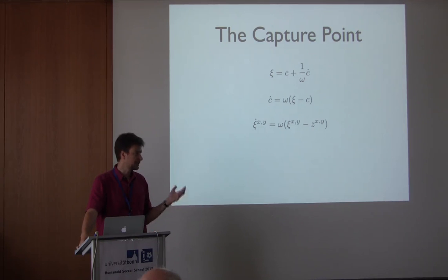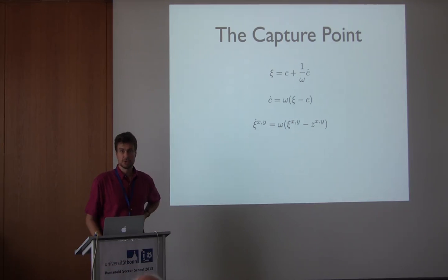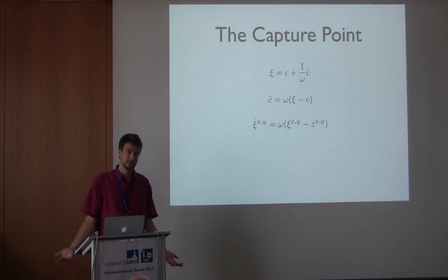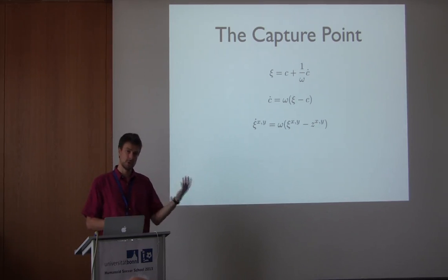And you can see that it's only now that you have viable impedance actuators, for trying to store energy and release it later. Because using only springs, how do you produce really good actuators? You have the series elastic actuators, which were proposed, I don't know, 15 years ago in the MIT lab. Well, not many robots use them so far. So people were waiting for viable impedance actuators. They are coming.